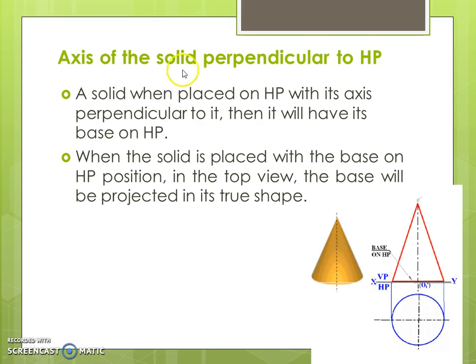So first, axis of the solid is perpendicular to HP. We are considering only the axis perpendicular to HP. So it will form the base position of the solids. Here, see, a solid is placed on HP with its axis perpendicular to it. If the axis is perpendicular to HP, the base will lie on HP.